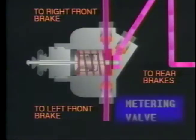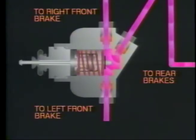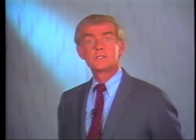To answer this question, you must understand the function of each component mentioned. The metering valve allows approximately 100 pounds of pressure to be applied to the rear brakes before allowing pressure to be applied to the disc brakes. This allows the rear drum brakes to overcome the return spring resistance so that, in reality, both the front discs and the rear brakes are applied at the same time. An inoperative metering valve would cause the front brakes to lock up.